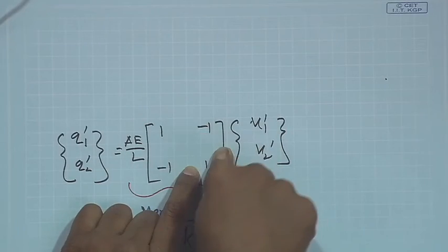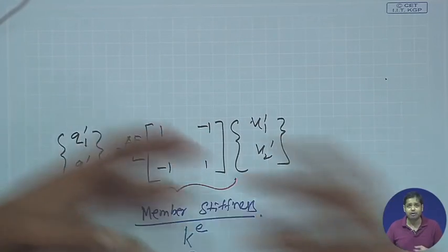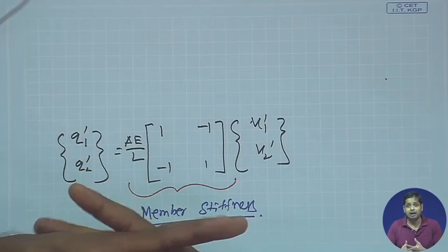Okay, what do we do about this stiffness matrix? We have a similar stiffness relation for all the members, but we cannot assemble them, we cannot add them as they are, because we have to transfer them onto the same plane, with respect to the same coordinate system. Only then can all this algebraic addition and subtraction take place. So now we will see how this stiffness matrix can be transferred to its global coordinate system. The steps will be clear if